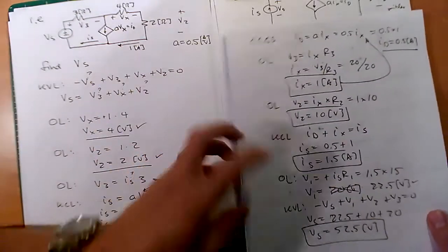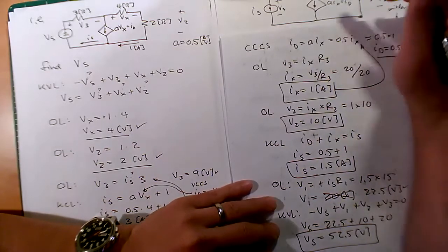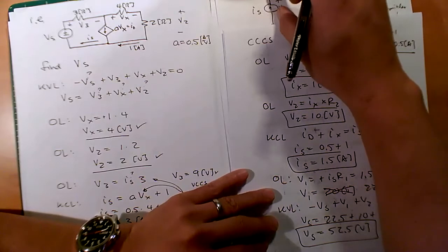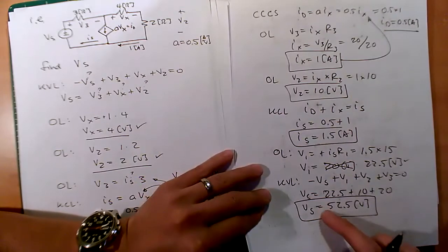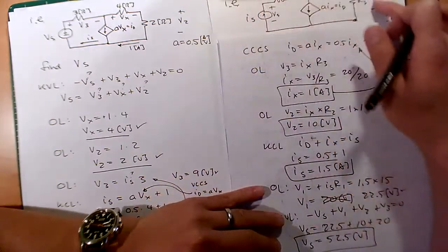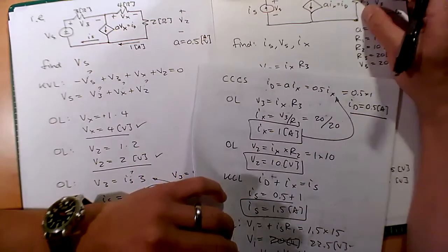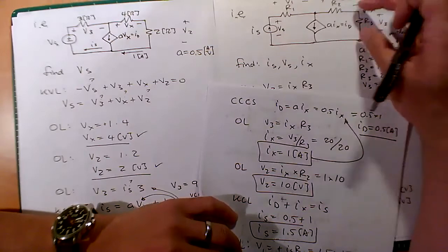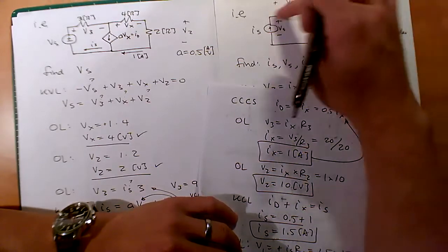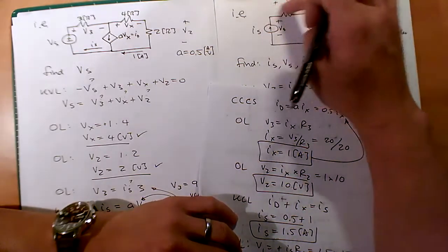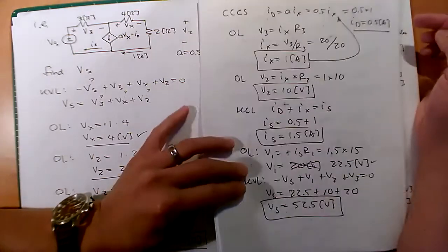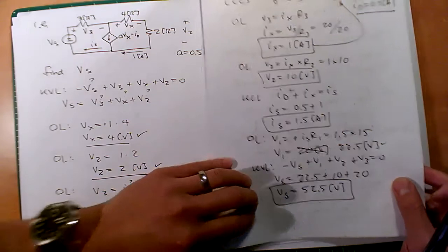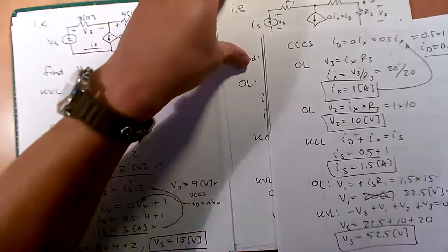But let's just double check. Does that make sense? If we're getting positive currents through here, yeah, this better be a pretty high voltage. Yeah, it's good that this came out to a positive sign. All right. And then this is 20 volts. So whatever this is has to be bigger than at least 20 volts. And then you got these other resistor drops, these voltage drops across the resistor. Yeah, I buy that. That seems to make sense. Okay, good. All right, let's keep going.